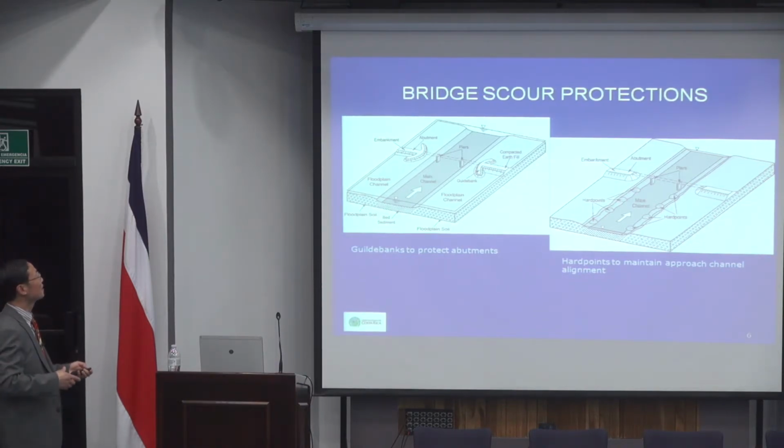Basically, these are just a group of rocks together, or sometimes you can have a group of timber piles together to make the water more resistant. In other words, provide more friction to slow down the water against your abutment. That will protect your abutment. That just provides hard armor, a lot of rocks to prevent the water from cutting into that abutment.